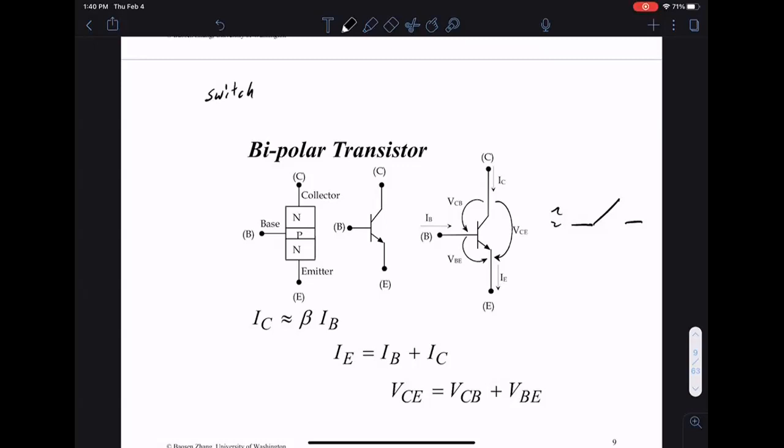So in the past, we have been using bipolar more often than not. But today, there's a technology shift towards using more MOSFET. MOSFET can be made smaller, with lower loss, more efficient, and so on. So if you go into industry now, you may see MOSFET. Don't be surprised if you see a power transistor circuit using a MOSFET. It's getting more popular. But bipolar is, for example, what you use in the lab if you take 351. It's easier to make, a bulkier, cheaper version. So that's our bipolar.